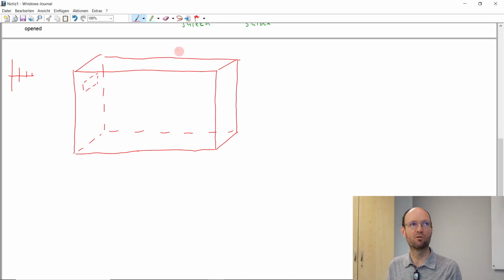And we have signals going back and forth, and so we might get standing waves. The simplest standing wave, or the largest standing wave that we could get, is one that has 0 at the wall, of course, and 0 at the other wall, and that has the maximum in the center. This would be the first cavity resonator dominant mode that we can get.